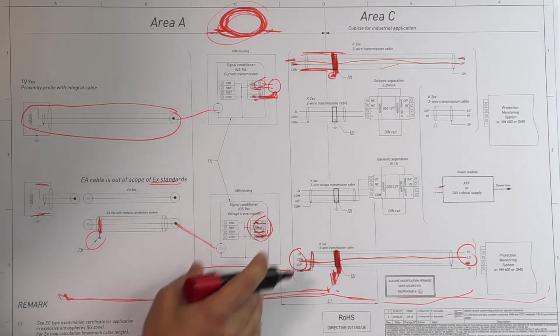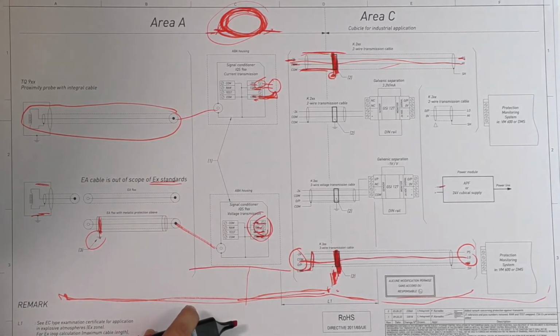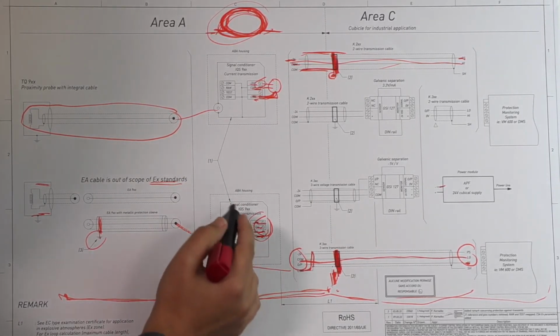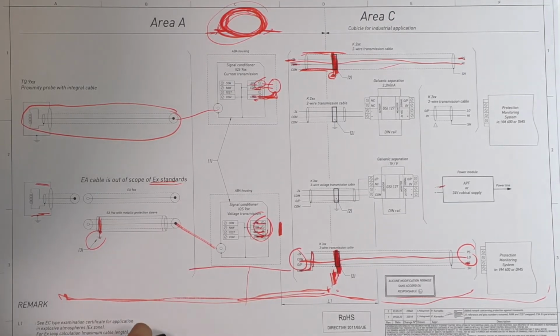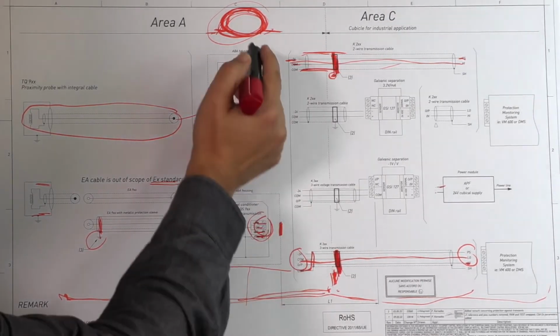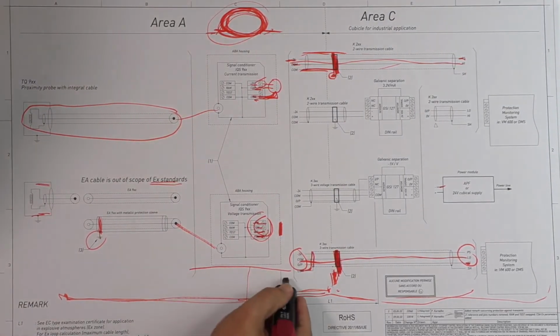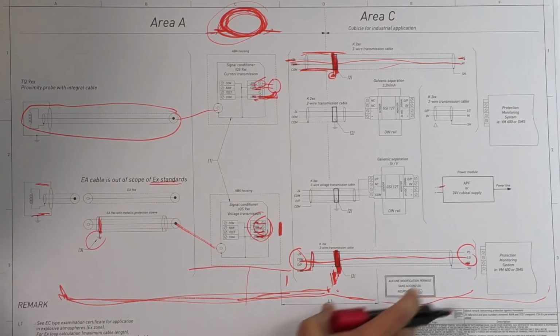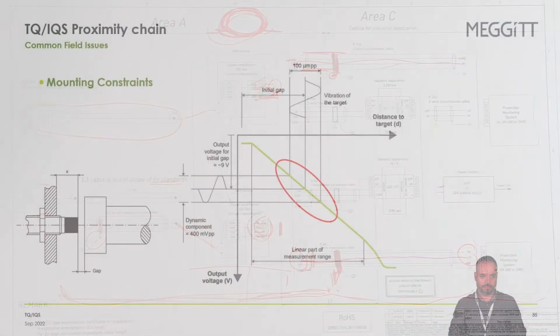They should be very well connected, short cables, proper cables. And if you have housing, make sure that all your strain relief protections are designed so as not to cause excessive deformation of the cable. This part again floating, and this part connected to the ground.